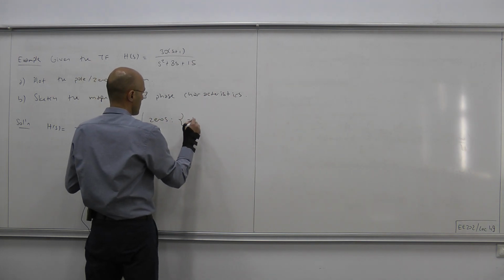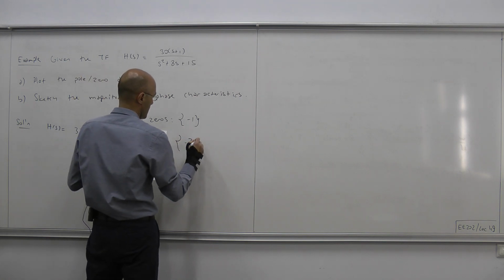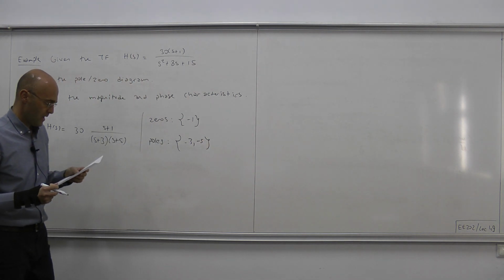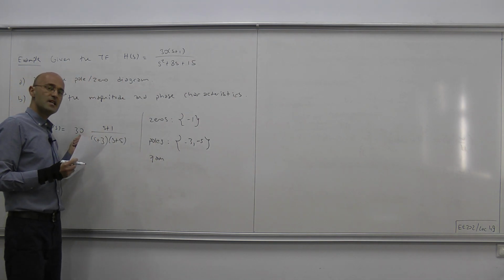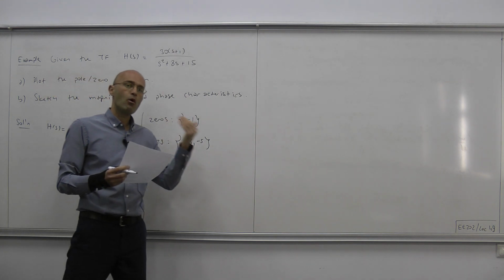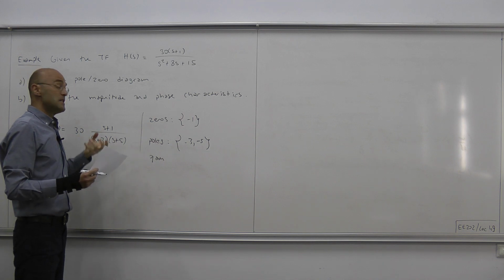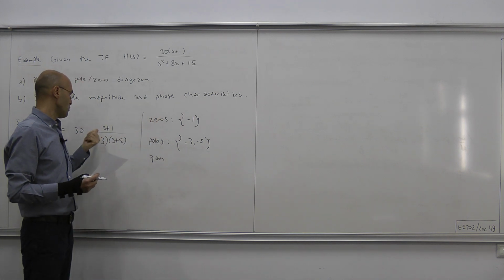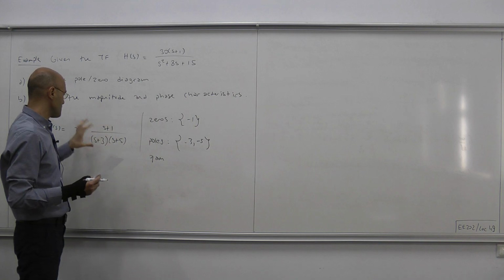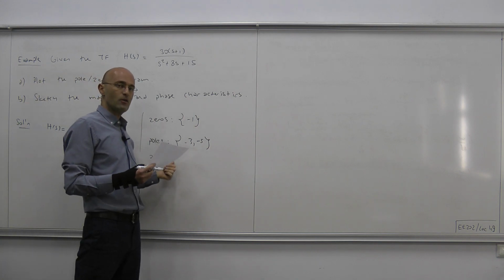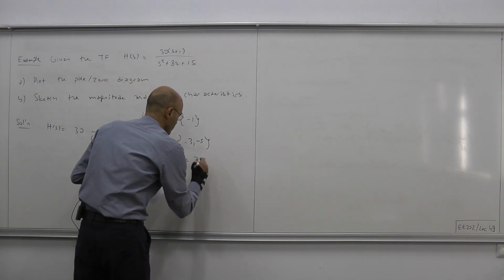Okay, so therefore zeros, -1; poles at -3 and -5. And as for the gain, the gain is what appears multiplying the fraction when you write both numerator and denominator polynomials as monic polynomials. Okay, the highest order terms, s here and s squared here, are 1. And then that thing is multiplied by something, and that something is what we call the gain of the transfer function. In this case, the gain, call it k, is 30.